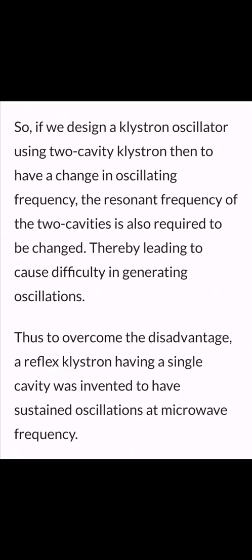So if we design a klystron oscillator using a two cavity klystron, then to have a change in oscillating frequency, the resonant frequency of the two cavities is also required to be changed, thereby causing difficulty in generating oscillations. Thus, to overcome this disadvantage, a reflex klystron having a single cavity was invented to have a sustained oscillation at microwave frequency.